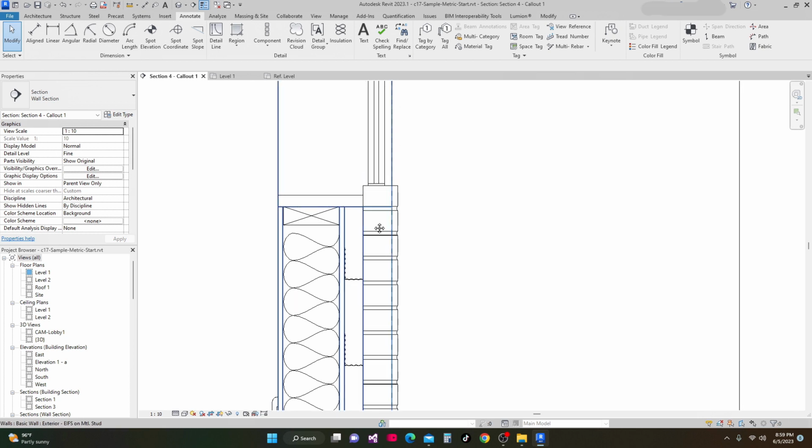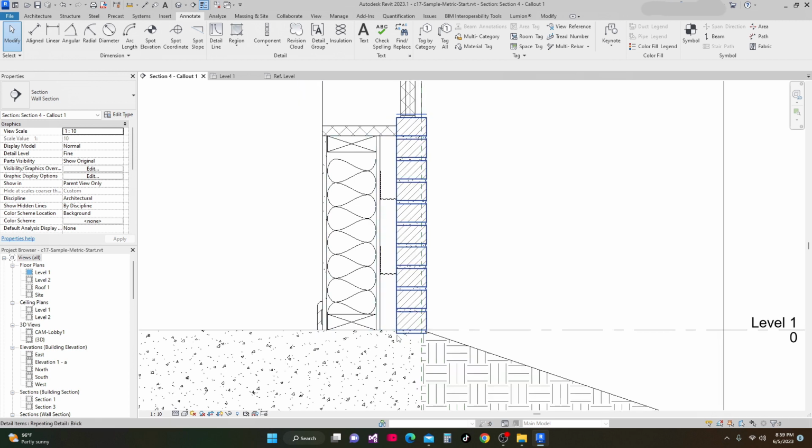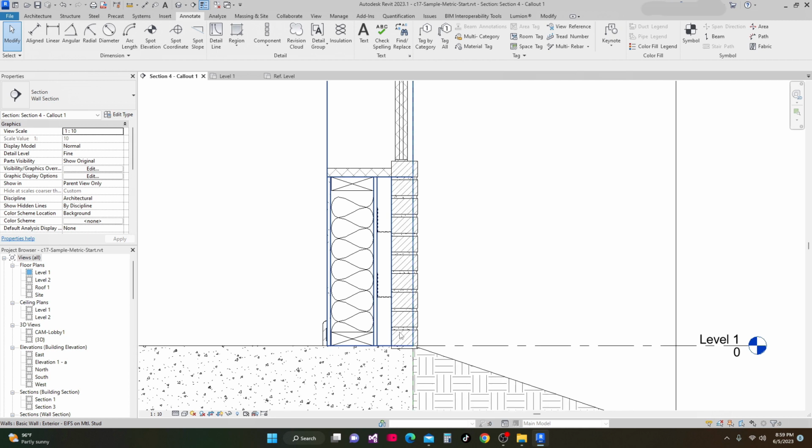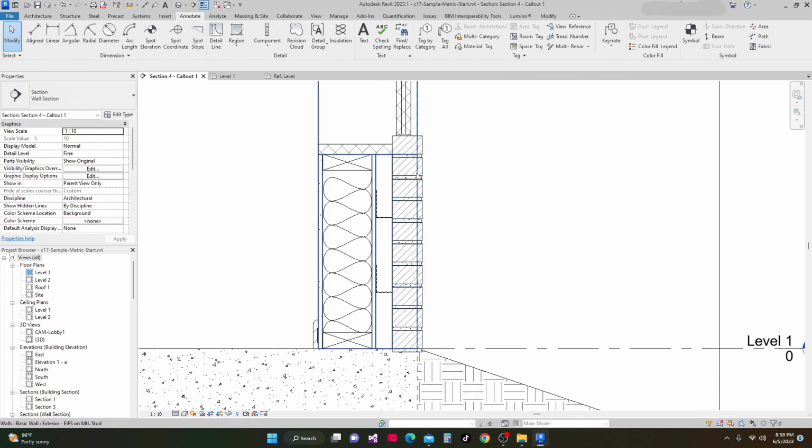So it means to say I have drawn this from here up to there. So this is the last component that my bricks will adapt. It will adapt only up to there. If inside is not selected, the last component will be drawn outside or overlapping the end point of the line. It will just be like what is here.